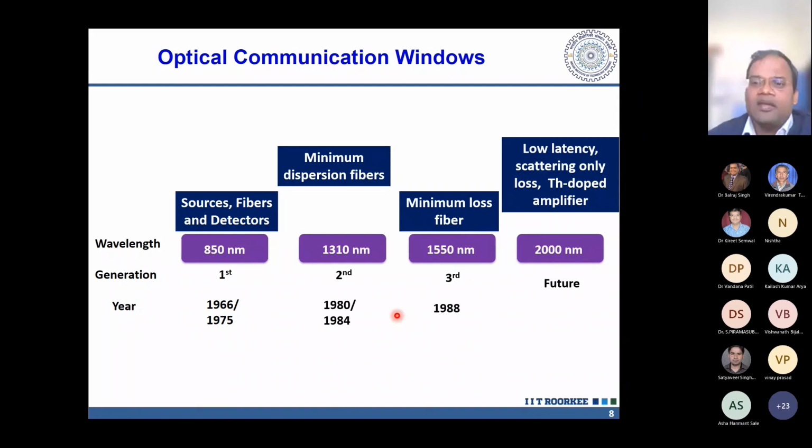So we can have low latency when light can go through air. How can we make such a medium? Using photonic crystal fibers, we can propagate light in air because that fiber has a core which is basically air. However, the scattering effect will still be there. Normally it is Rayleigh scattering, which goes as lambda raised to the power -4.